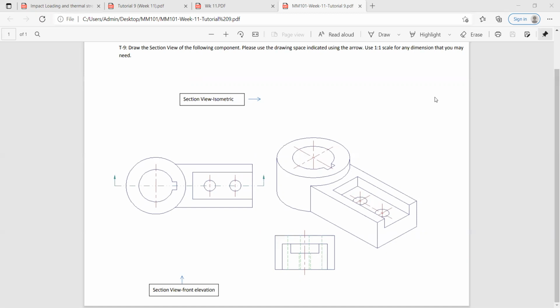Hidden lines are commonly used. Like in this activity here, we have hidden lines in this side elevation, but it's not always clear as to what the hidden lines are showing. Okay, in this case, we have 2 hidden lines side by side each other, and we're not sure. I mean, we can infer, but it takes a little bit extra work to try and understand or interpret these hidden lines and what they represent. So in these cases, the best option is to do a sectional view.